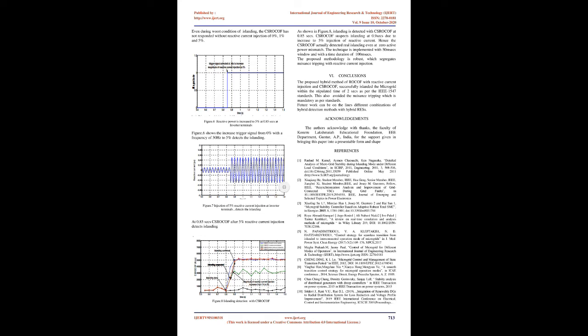To counter this gap, an active islanding detection method of injecting reactive current at inverter terminals while in grid mode is used. There is drift in frequency only under islanding. Otherwise there is no effect in frequency if grid is present. But setting a low value gives false tripping signal and at the same time higher value increases NDZ 14,15.